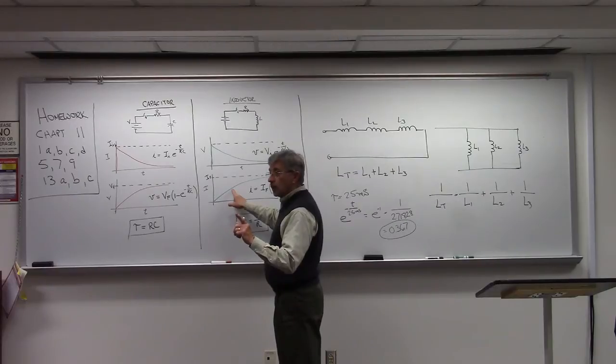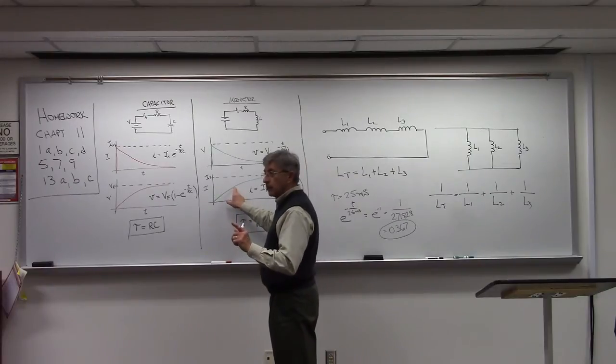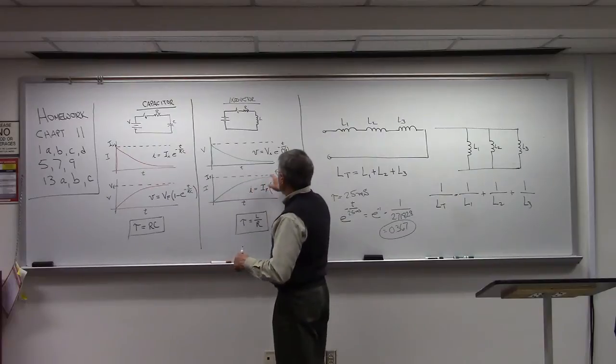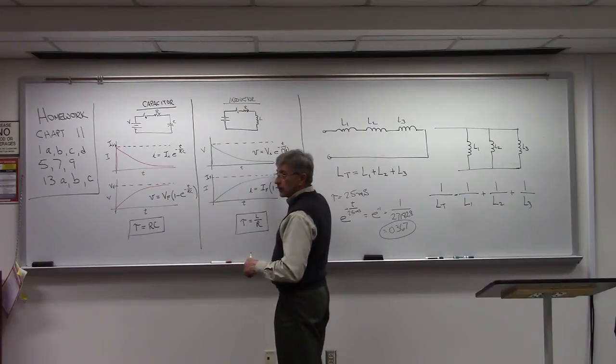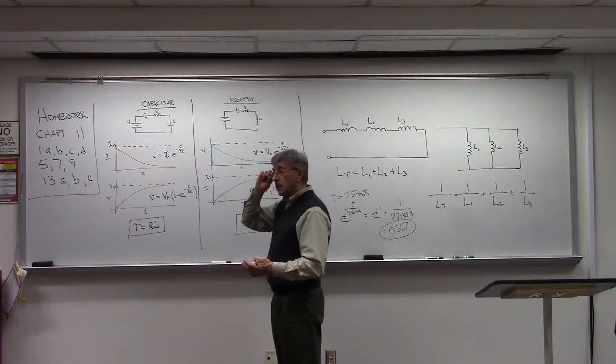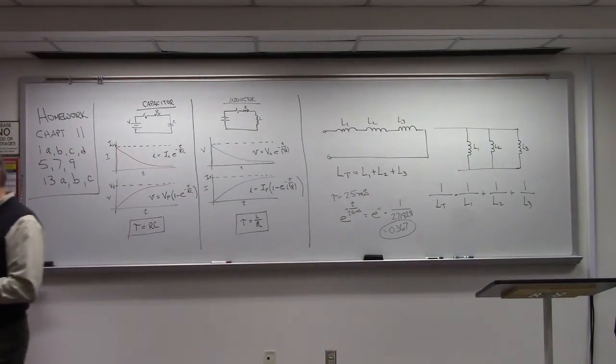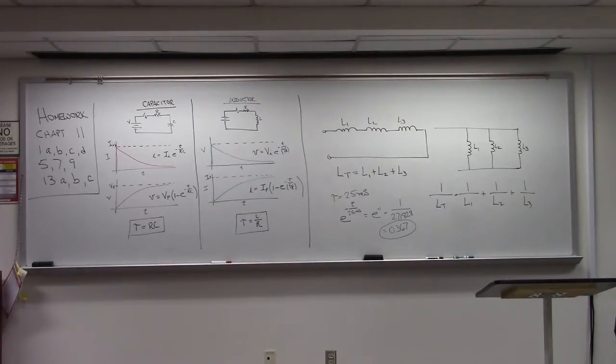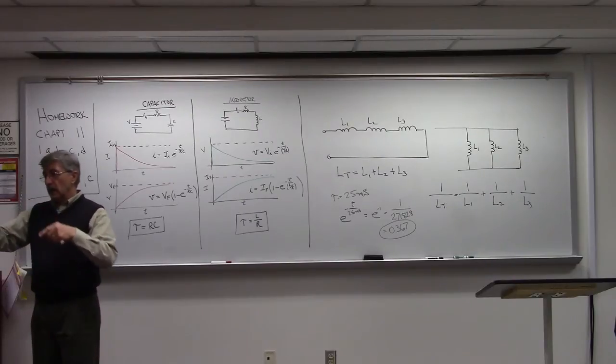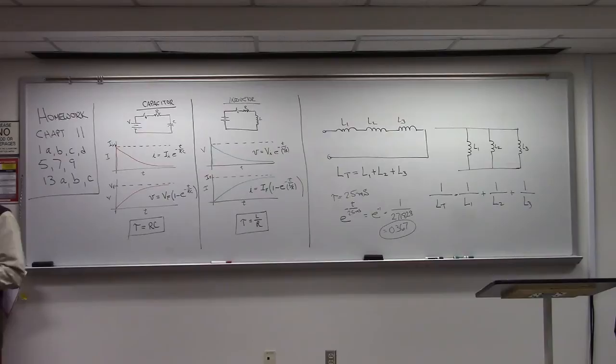So if you go 5 of those, 5 time constants, you are going to hit a point where this curve effectively reaches its maximum value. So take 5 times 2.5, what do you get? 12.5. You actually measured on your computer, remember that you put those two cursors, you measured 10.3, you calculated 12.5, and so you're close. All right?